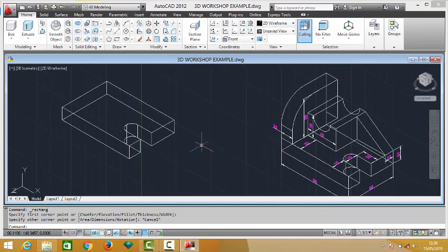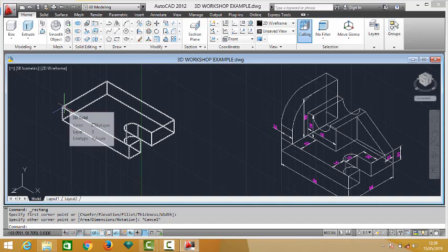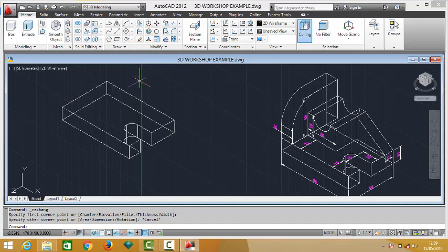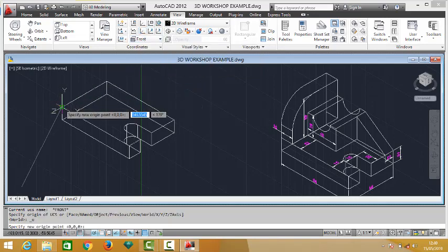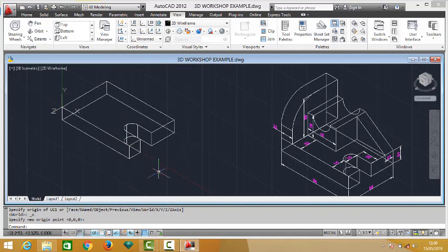You are just moving here and going like this. So what we'll do is that we'll place our reference, our XYZ origin to be here. So our 0, 0, 0 will be here. So what we'll do is we'll come down to the view. You click on this origin. When you click on this origin, the UCS will just snap to your hand and then you place it here. So this place is now our origin. This place corresponds to here. So right here we have 0, 0, 0.